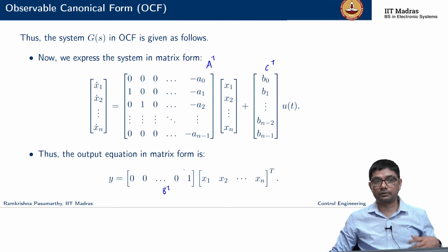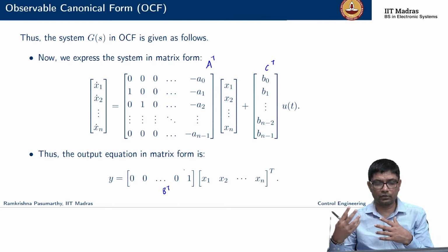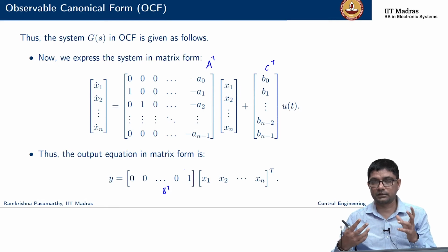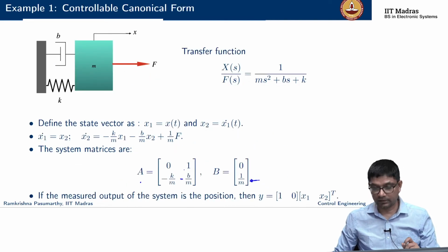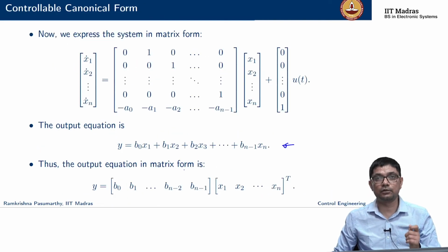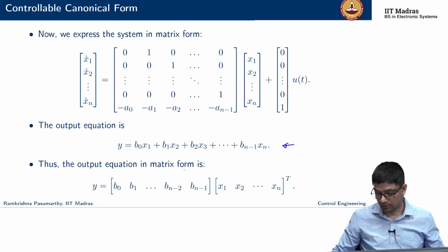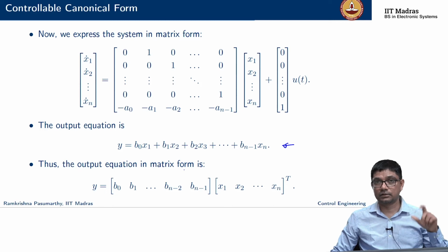So in the DC motor, we could control the speed with the help of just regulating the voltage. When I write the expressions in a controllable canonical form, it will be a little easier to understand how we can control the system, right? So whether or not we can control the system, or is the system, so to speak, controllable.